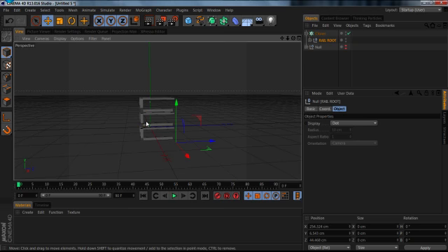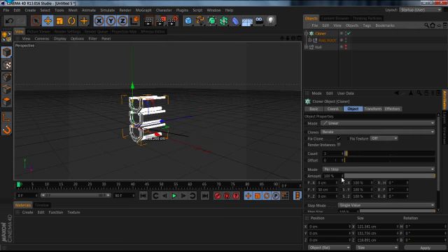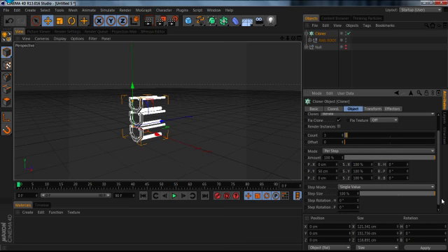railroad being cloned, but only that it's being cloned in the wrong direction. And as you can see, we have 3 clones, which is the count right here, and it's a linear count, which is what we need, only that they're being cloned in the wrong direction. So I'm going to zero that out, and I want it to be cloning along the z-axis, so it's XYZ.